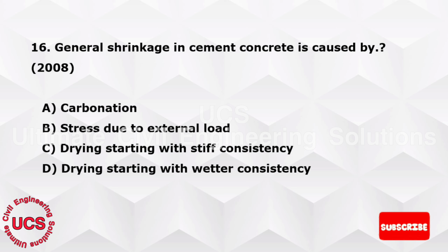Next question. General shrinkage in cement concrete is caused by. Options are option A carbonation, option B stress due to external load, option C drying starting with stiff consistency, option D drying starting with wetter consistency. Answer is option D, drying starting with wetter consistency.